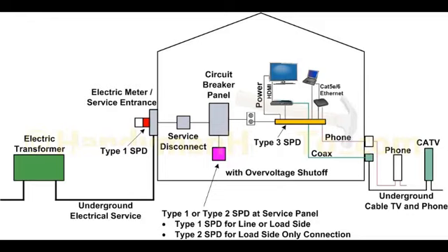All these are fed by copper, and surges will have an effect over time if you don't have a type 3, a type 2, or a type 1. Now many customers will focus on a type 2 or a type 3. It's important to have both. This type 2 will protect the unit from anything coming into the facility. The type 3 will protect your sensitive and expensive electronics from switching transients and things that go on inside.